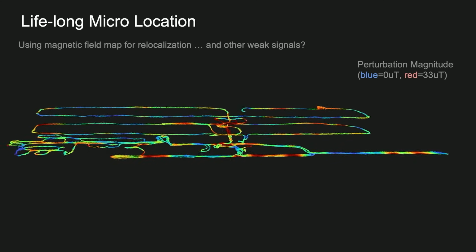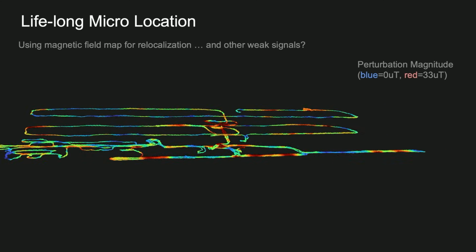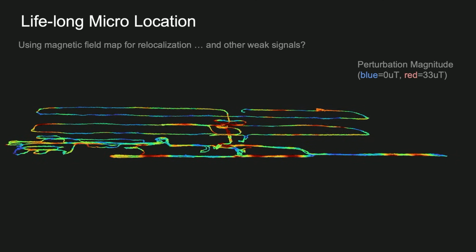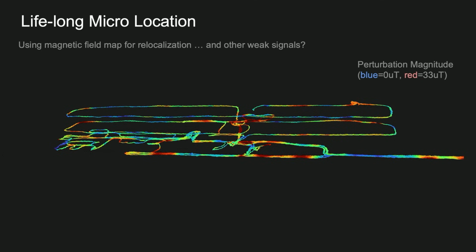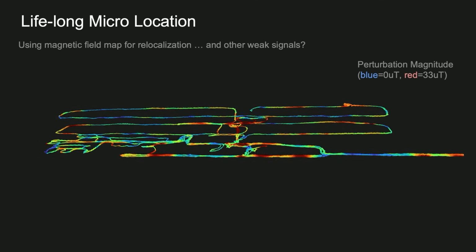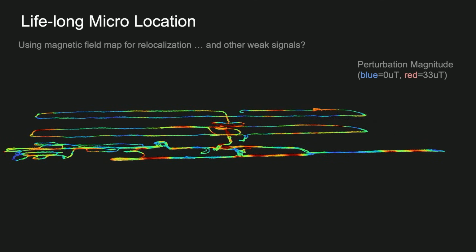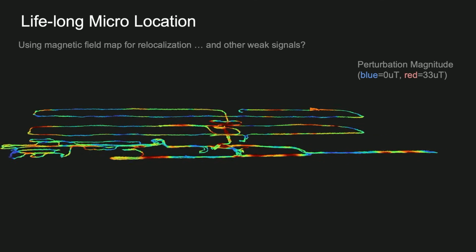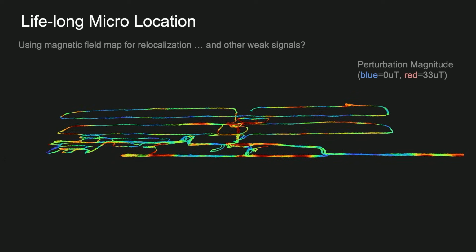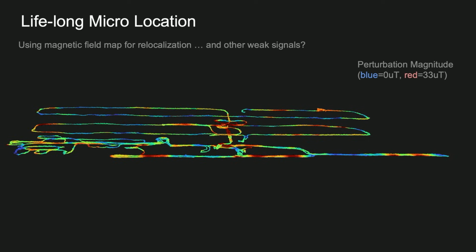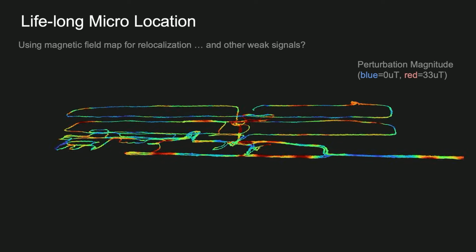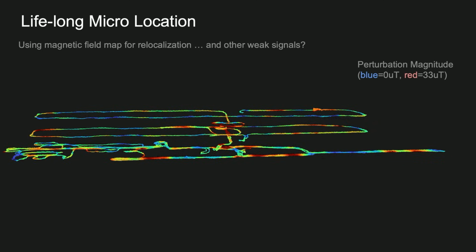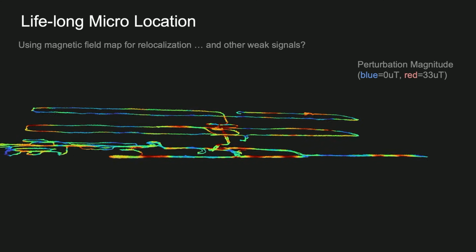But even if you are interested in the localization problem, having this kind of very good odometry trace can unlock some new kinds of information. There is something a lot of people talk about, but nobody really made it work, which is magnetic mapping in buildings. The magnetic field in buildings cannot really be used for measuring north. But if you map the magnetic field magnitude on the 4-hour trajectory I showed you in the same building just before, you can clearly see that there are areas of the building that have a very specific magnetic field magnitude.